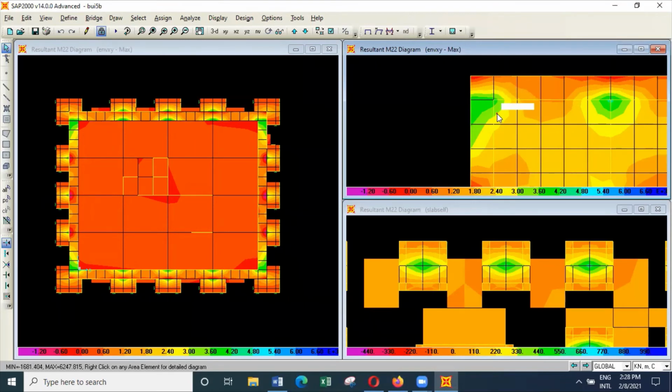And here you can see the bending moments are fairly high, something like 3,489, or it can go up to 3,927. And the biggest problem that you get in this type of situation is the punching shear and the shear around the load. And in addition to that, the way that we have arranged the transfer plate, you can see this particular column is at the edge.